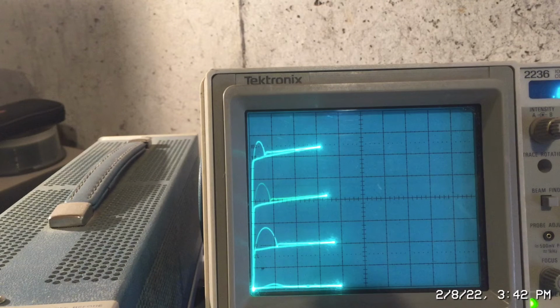So it said we should be somewhere between 10 and 150. We're at 32.5. There is a lot of variation in these devices, and a pretty wide range for beta. So that's why it's important, again, for a push-pull design to match these transistors so that they're each doing the same amount of work, conducting the same amount of current, to kind of share the load. And as I mentioned, the breakdown voltage is about 18 volts.